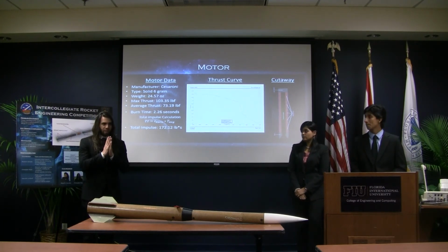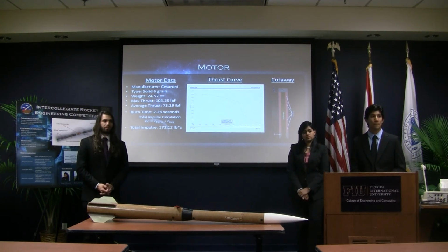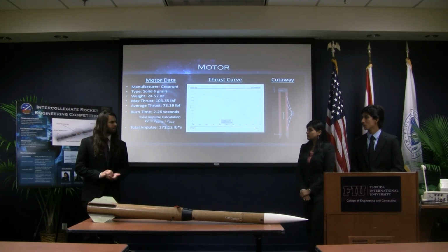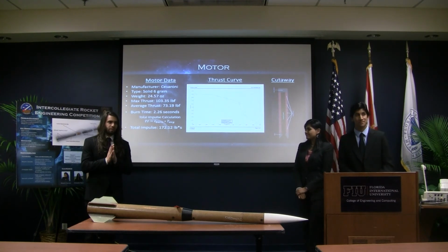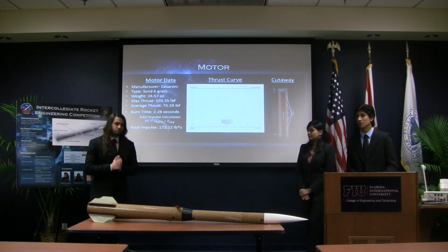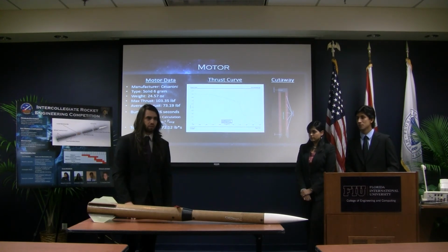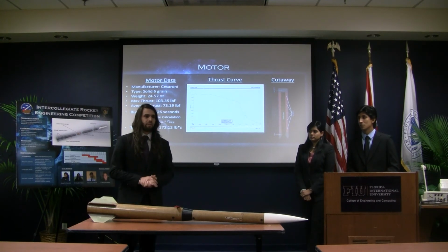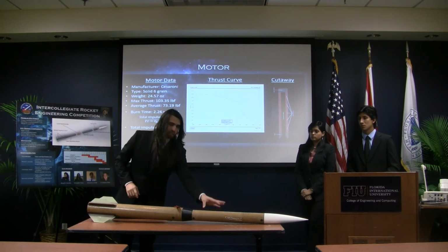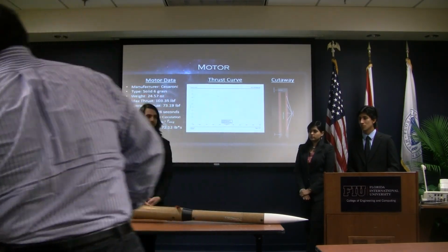Oh, you're talking about the line of the rocket. Are you shooting for a hyperbolic type of curve, or are you shooting straight up? No, we want to keep it as straight as possible, and that's one of the reasons we're keeping the stability low. Because the lower stability means that it won't react to the wind as much. So that's why the center of gravity is about right here, and I think the center of pressure was just 2 body diameters lower. We make sure that as much as possible we keep the weight centered throughout the rocket. The electronics are all on a sled, which is dead center as much as possible.